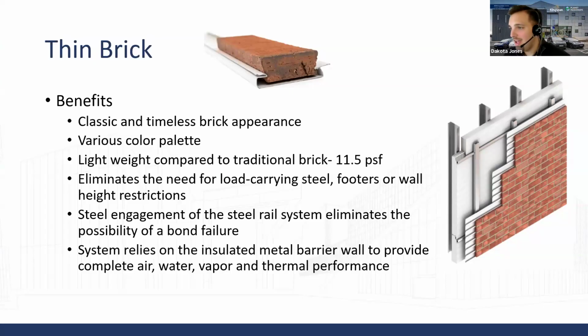It's fantastic. Essentially, it's a tracked system that you can attach onto a rain screen with an air gap in the back, just like you normally would. And then you can take these bricks that are profiled so that you can snap them into place. And then, I mean, a cake maker could come through and pipette the mortar around them, and they look like brick, they act like brick, they are brick. It's just thinner and installs quicker. So really popular, like I said, growing in higher education.